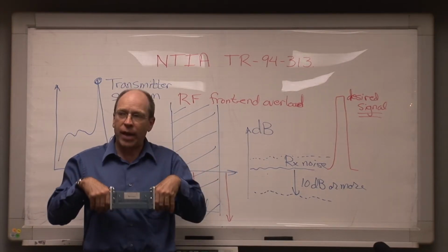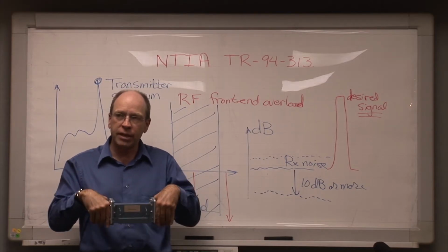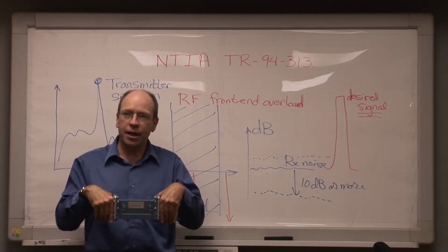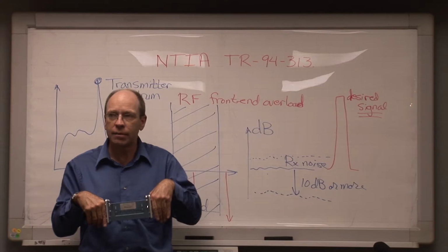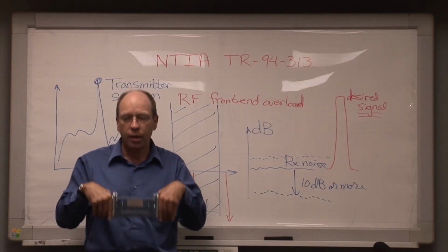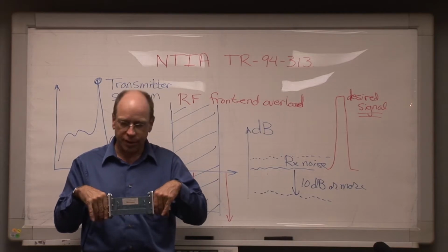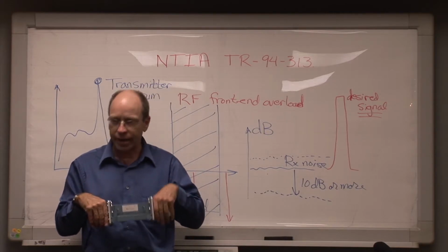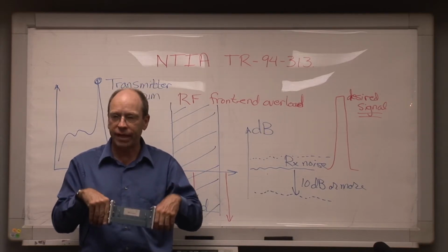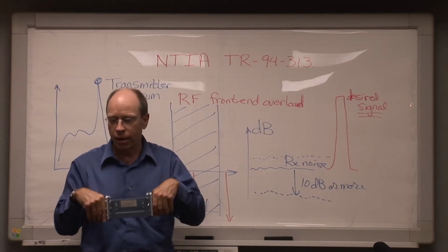But the point is that this is a bandpass filter which will pass energy in the receiver's desired band of operation and rejects energy to the tune of 60 or 70 dB or more outside the band of the receiver operation. You could use a notch filter to specifically reject one transmitter out of the band, but then you'd have trouble if anyone came up on a different frequency out of the band and could cause the overload problem.